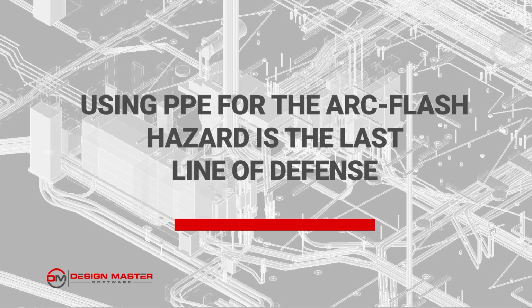You also need to keep in mind what the calculations are doing and what the level of protection that's being attempted is. The 1584, the 2002 talks about this a little bit in the introduction. They changed how they talk about this, but I like what they say in the 2002 a little bit here. It says that when we're used, PPE for the arc flash hazard is the last line of defense. So the idea is that if you have arc flash, you need to have the PPE on to protect you.